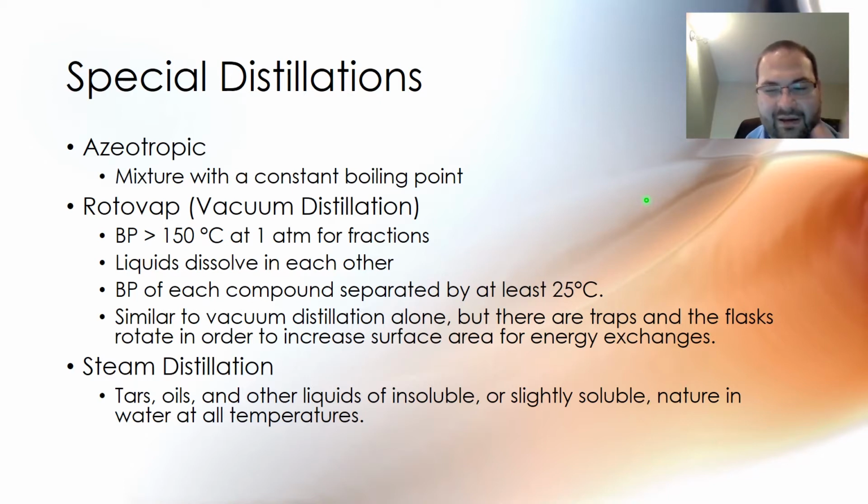You pick one or the other. But you can use this vacuum to separate compounds with those degree separations that have boiling points greater than 150 degrees Celsius at 1 atmospheric pressure. So you can basically reduce the time it would take to use all of that energy, because those thermo wells